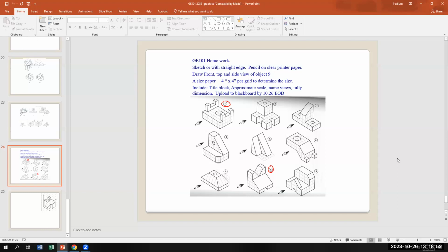The bottom slot that looks like a triangle. If it's not called out how deep the slot is, then it goes all the way through. And that's typical on all drills. If a hole is called out as a half-inch drill, then that goes all the way through, unless they say half-inch drill, quarter inch depth. Then you have a bolt going in quarter inch depth, right? So on all these kinds of things, if it doesn't say, then it goes all the way through.